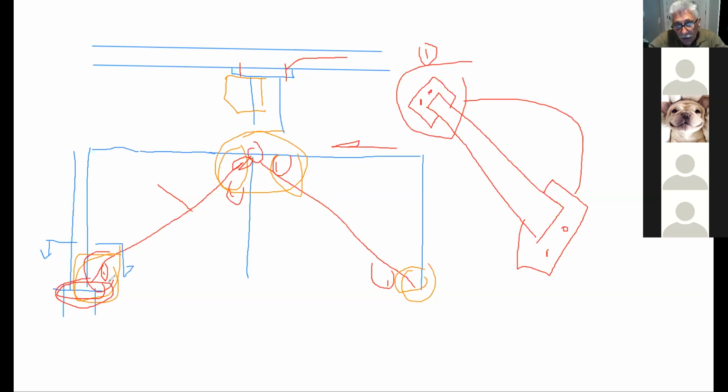Now, in theory, this anchor bolting here, if you were designing this anchor bolting, you would have to calculate the tensile force that is going up your frame and make sure that the bolts here can actually resist and create a downward reaction. But that's another story. Okay? But we're not going to go there.